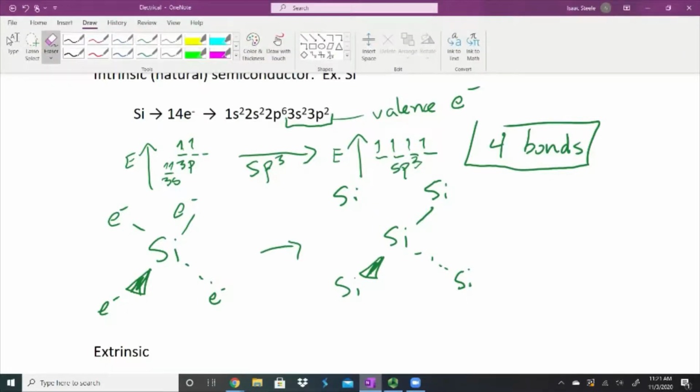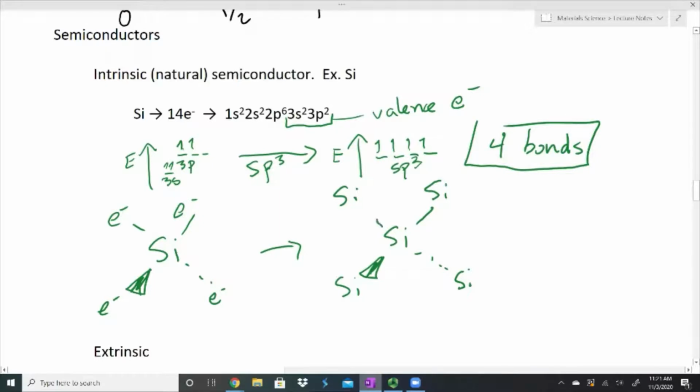What's going to happen is this silicon has an electron, and this silicon up here has an electron. But as I push electrons through this material, as I try to have conduction go through here, a different electron could come and basically sit in this silicon atom, and it would bond. But it could delocalize and move to this silicon atom to the right, and a new electron would sit on the silicon atom on the left. And slowly I can promote these electrons through. And it does take a little bit of energy for this to happen.